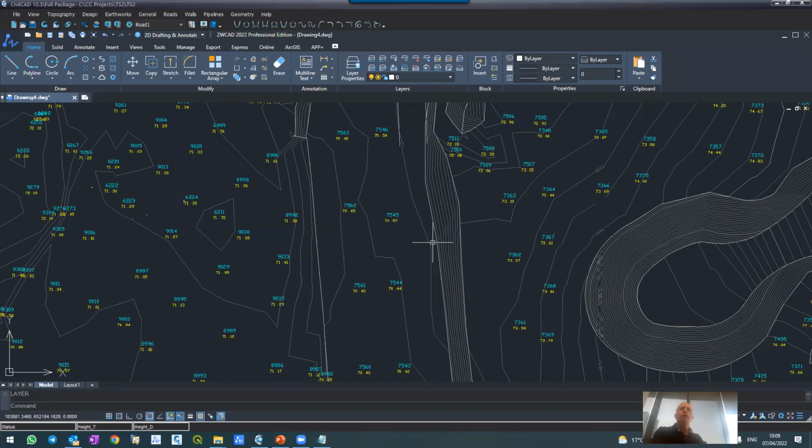Yeah. So for your question, what I loaded now was a plain TXT file, but we have many. We are supporting CSV files from Excel, obviously. We are supporting Leica format, GT7. We're supporting TopCon native. We are Trimble native. As I said, pure TXT is also okay. Comma delimited is also okay. Space delimited.